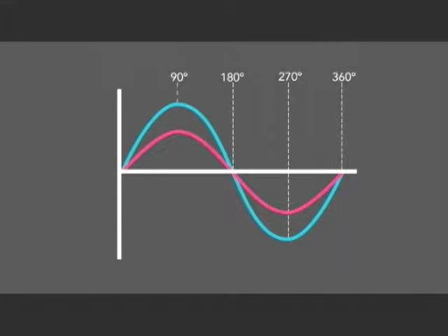If capacitors are added to a circuit, part of the current is made to lead the voltage by 90 degrees. Capacitive current always leads the voltage by 90 degrees. Since capacitance has the opposite effect on current to inductance, the capacitive current cancels out a like amount of inductive current. The more the inductive current is canceled, the greater the improvement of the power factor.